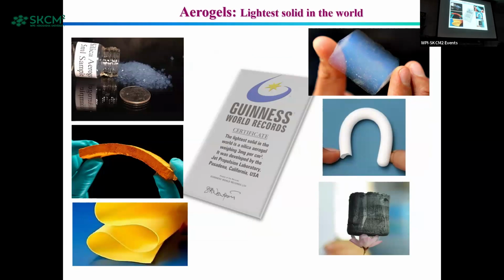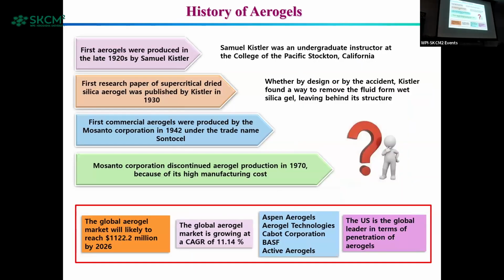Here you can see granule-type, silica-based transparent aerogels. One can synthesize monolithic aerogels. Flexible polymer aerogels are there. One can synthesize polyamide aerogels, and MTMS-based or silane-based flexible aerogels as well. This is the silica aerogel first synthesized by our Professor Rao, my PhD supervisor. It was the first flexible silica aerogel, reported on the aerogel.org website also. One can also synthesize graphene-based or carbon-based aerogels, wherever we are going to use the material.